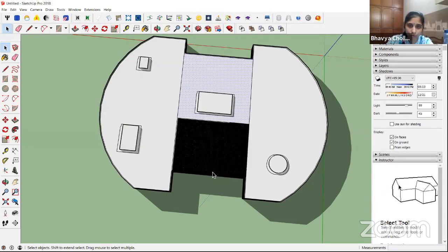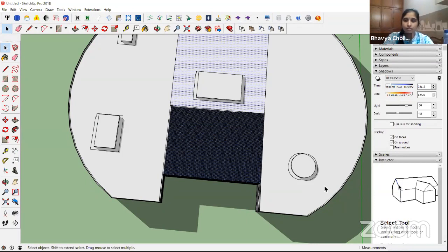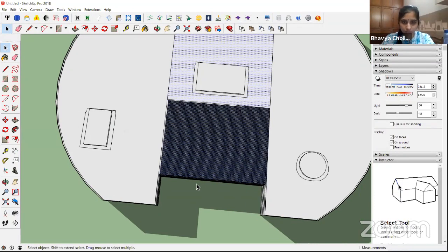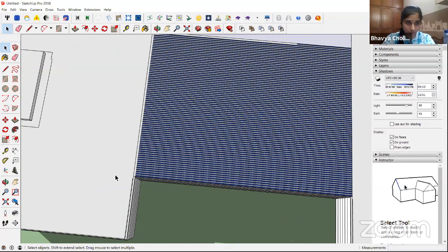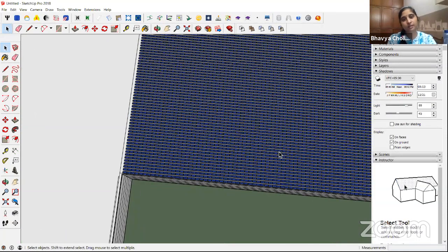You can see the modules, I guess, right? Now you don't want such depth. Again, you see the last row is there. Ma'am, how to determine the spacing between modules? Okay. Generally, there is a default guide setup for the spacing between the modules and the pitch configurations. Module to module spacing, we go with 40 mm spacing, and then the string to string configuration also. We go with the complete consideration here.